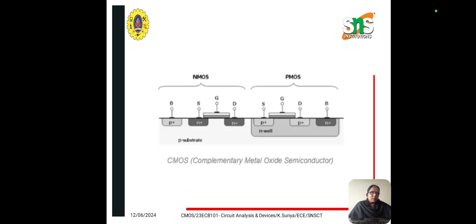So the main advantage of the CMOS over NMOS and bipolar technology is the smaller power dissipation. Unlike NMOS or bipolar circuits, a complementary MOS circuit has almost no static power dissipation. Power is only dissipated in case the circuit actually switches. This allows integrating more CMOS gates on an IC than in NMOS or bipolar technology, resulting in much better performance. A complementary metal oxide semiconductor transistor consists of p-channel MOS and n-channel MOS as shown in the figure.